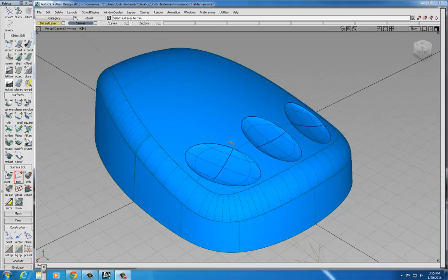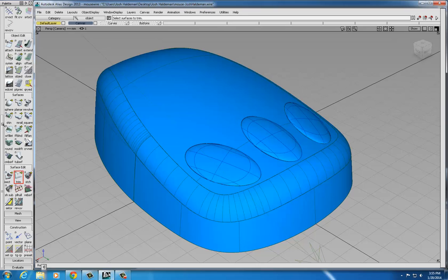All right, this is the last part of the computer mouse, and we're going to just simply place and size and position the buttons. We placed these on a layer that we shut off, so the first thing we need to do is turn that layer back on. Don't be concerned here if it looks like our housings are coming back, because we haven't sized them yet. But go to the buttons layer, choose the word visible, and they'll pop right back in.